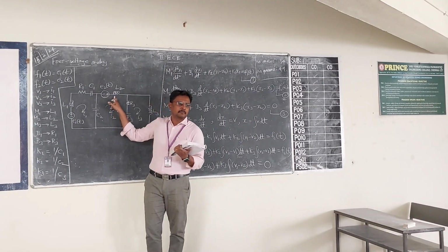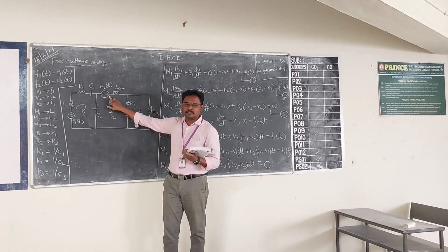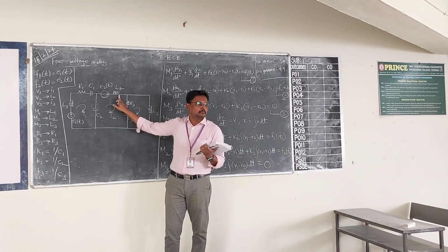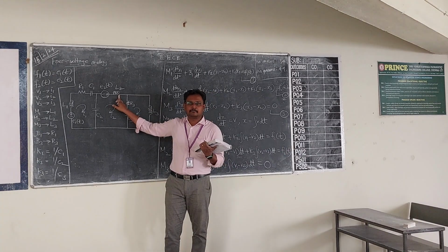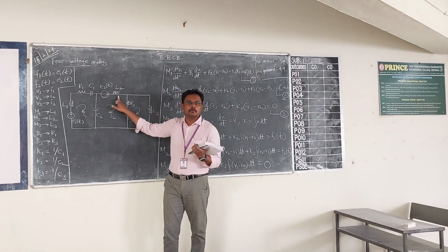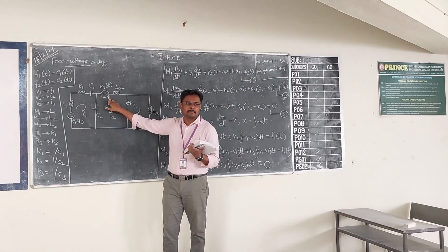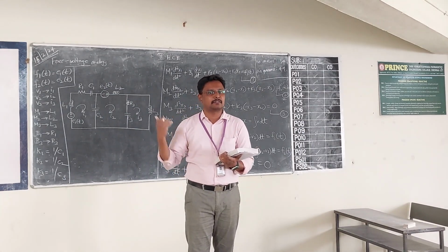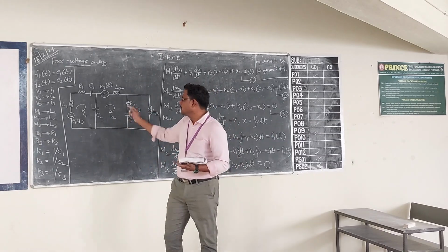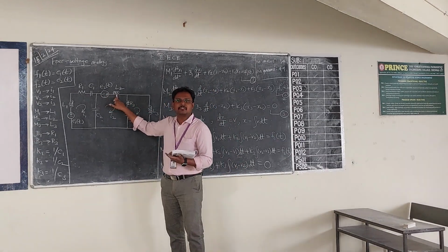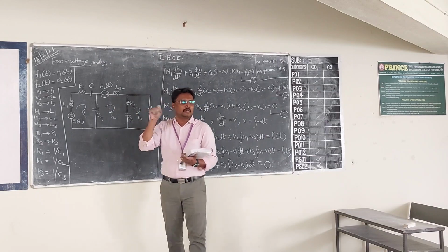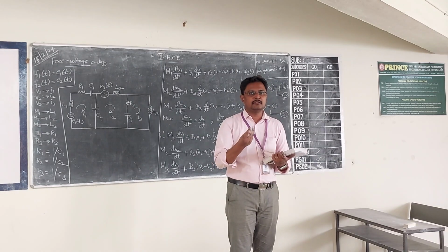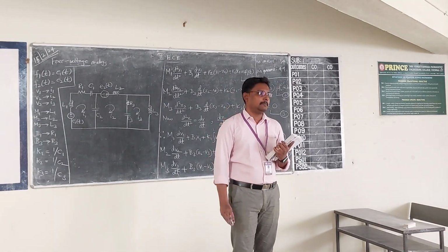See the second loop. Here the plus sign represents the applied force to mass 2, and mass 2 is represented as the inductor L2. The plus symbol represents that a force is directly applied to the corresponding mass. The plus sign should be attached to the first end of the inductor, meaning a positive force is applied to the corresponding mass element.